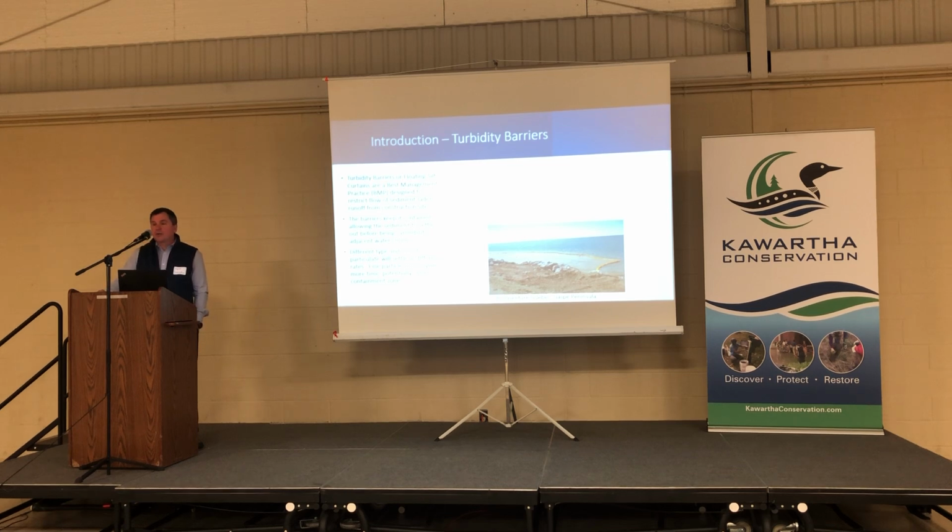Turbidity curtains are best management products, and they're designed to restrict the flow of sediment-laden water from the workspace. If you look at the picture on the right-hand side, the barrier is installed in an arc-type configuration. The workspace just adjacent to the shoreline is generating the silt, and the containment area inside the curtain is providing sufficient retention time for the sediments to settle out.